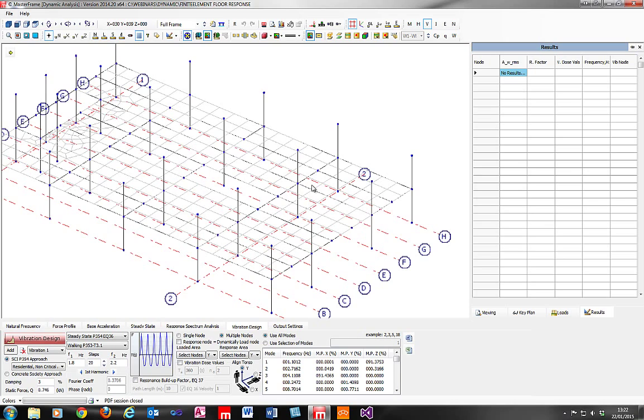There are a lot of combinations. In the initial instance, it's probably fair to assume that the worst response factor at a point occurs due to loading being applied, or excitation force being applied, at that same point, which is what this checkbox is all about.